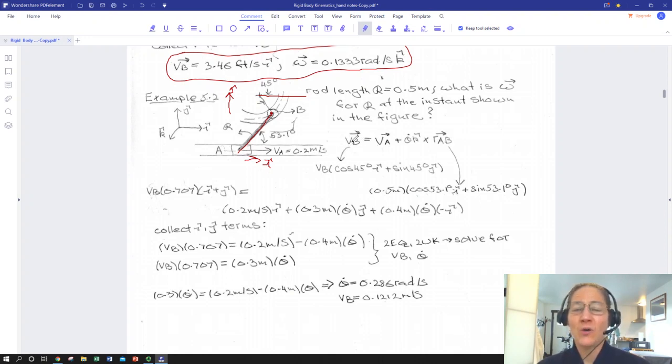Okay, we know the direction of the velocity of B at that instant in time. That's where we pull in this 45 degrees. It's instantaneous velocity, so we have to think like calculus students. At that instant, this point is heading right this way. It is tangent to this circle at that point.